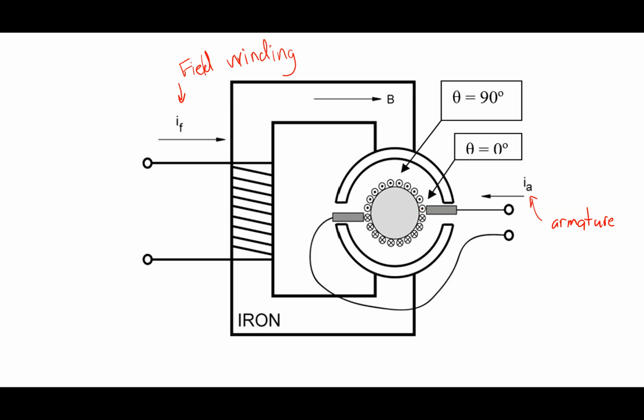That thing is called a commutator, right? And this is where I sub A goes in. And then over here, these two pieces are how I actually connect to the rotor coils, okay? In reality, this thing functions like a mechanical version of a rectifier, right? I don't want to get too into that, but basically call this guy a commutator. What he does is he's basically taking DC current and feeding that DC current into these windings, okay?